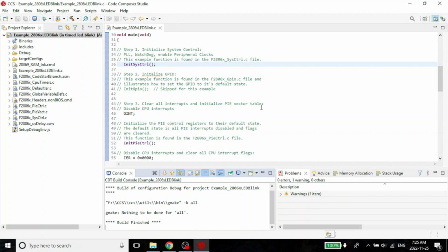It is extremely important, because if you do not have flashing LEDs, there is some problem with your system. It could be an error in your Code Composer Studio. It could be a mistake, something with your hardware kit. It could be that you have not established a connection successfully with your microcontroller kit. It could be any number of reasons, right? So, it's very important that this lecture is successful, that you are able to see exactly the same flashing LED I do. If that's not working, please do post in the Q&A forum, and I will try my best to help you out.